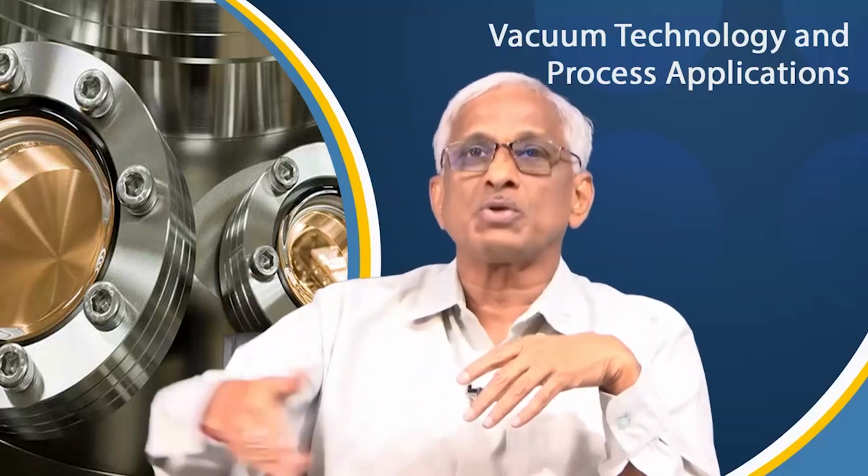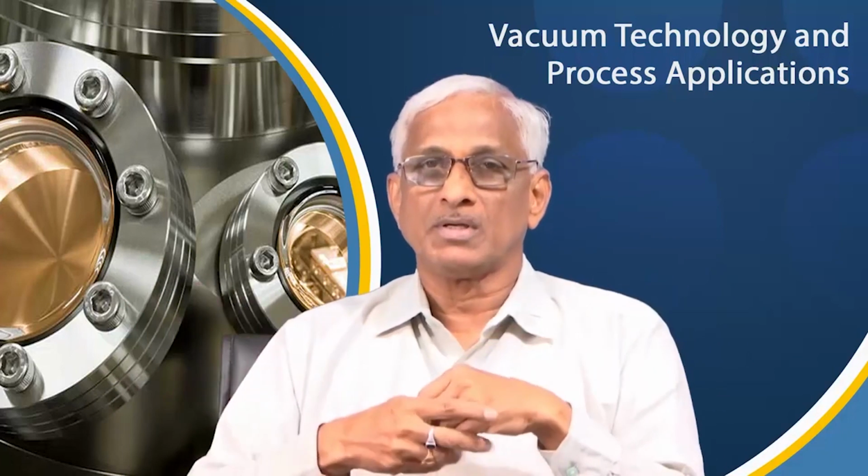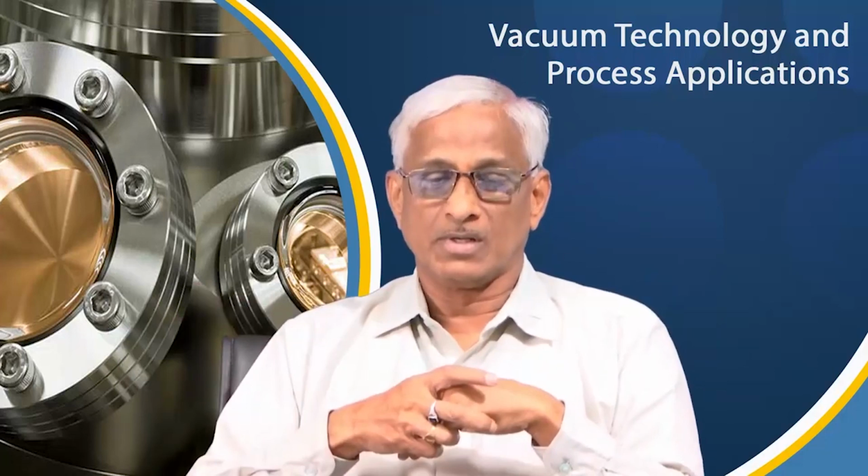Metallurgical, metal coatings, engineering coatings, the better the background vacuum, then during the actual evaporation, the background impurities are less to that effect. So, you will get a quality level. Similarly, semiconductor processing or semiconductor circuits, chip manufacturing, etc. The better the initial base vacuum, the better the quality of the chip will be. So, keep this in mind as also a physical concept involved in it. Why do we have to go for high and ultra high?